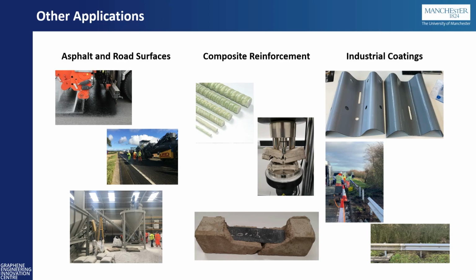So we have our parking bay, we have a gym floor, we have a big suspended floor down at the Mayfield depot in Manchester, which made the news, you might have seen it. And that's a big suspended graphene-enhanced concrete floor, which is now a roller disco. So it's getting some abuse, it's been rolled over a lot. Again, these are low-risk structures, and we need buy-in from industry to help us do these kind of living lab pours, anything that's low risk or temporary structures. These are the ways we can look at the real-life situation of using graphene concrete.